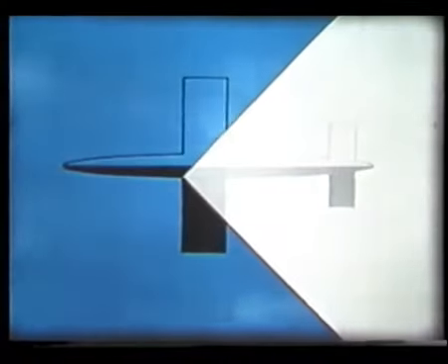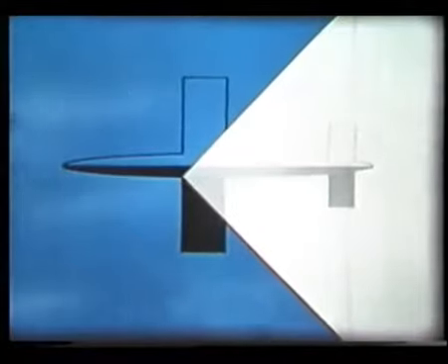But as with subsonic and transonic flight, sweepback is very important in supersonic flight. Look again at the single point moving supersonically. The air is undisturbed everywhere ahead of the marked lines. But behind them, in the white area, the air is affected. Now suppose the point is in fact the wing root of this straight-winged supersonic aircraft. The air has no warning of the wing's approach.